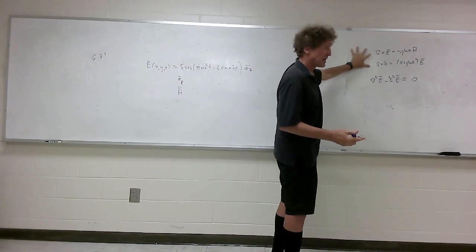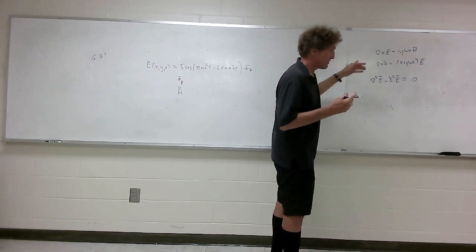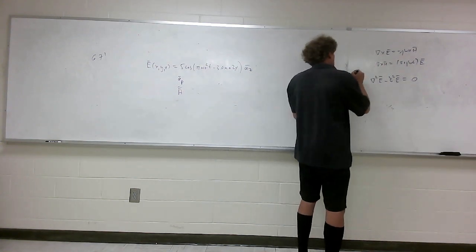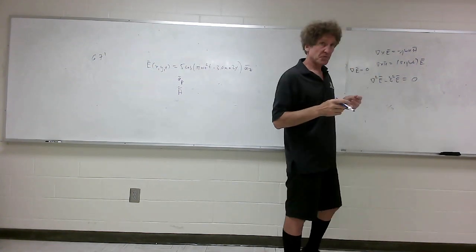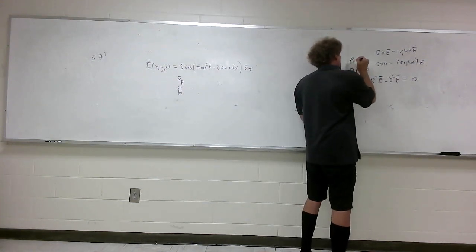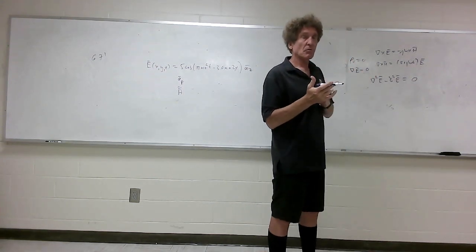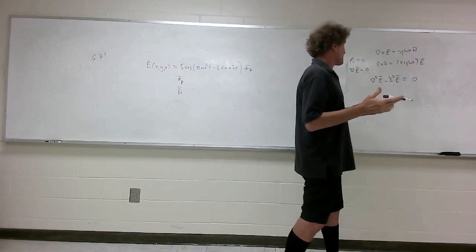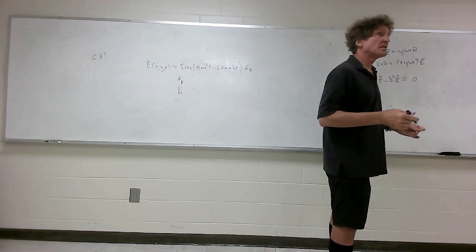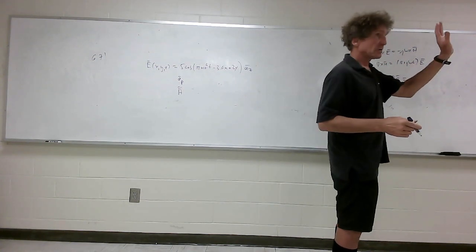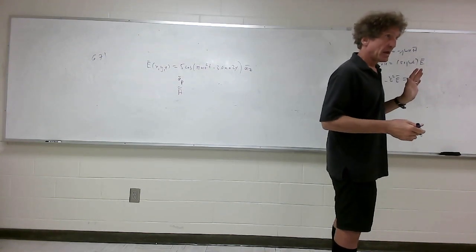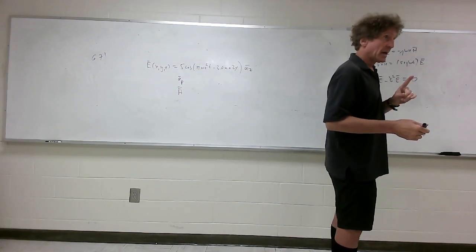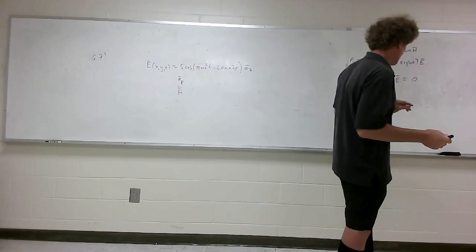So when we have this, we take another curl of E, then we substitute in that, then we do a vector expansion. At this point, we assume divergence of E equals 0, rho V equals 0, which means it's charge free. Do you all remember this? I'm going quickly through this. Then we moved into the assumption that the E field, or the propagation phenomena we're talking about, is a long way from the source, and it only varies in one direction, and the polarization is only in one direction too.